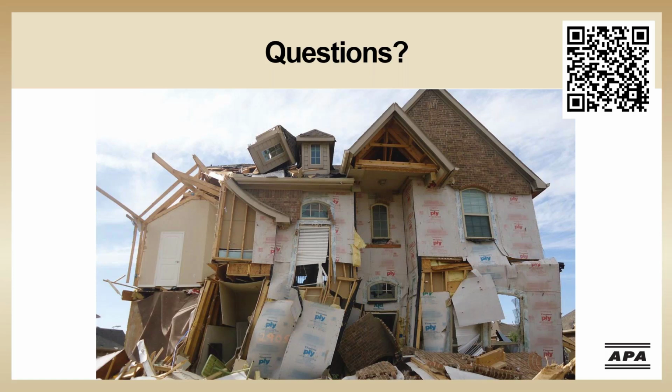A lot of pictures you showed of damage were from very high wind speeds. Is it realistic to expect a house to be able to survive wind speeds that exceed what is specified by the code? In a lot of the cases when we do look at wind events, what we see are houses that have been damaged in situations where actually the wind speeds were still within the code specified minimum.